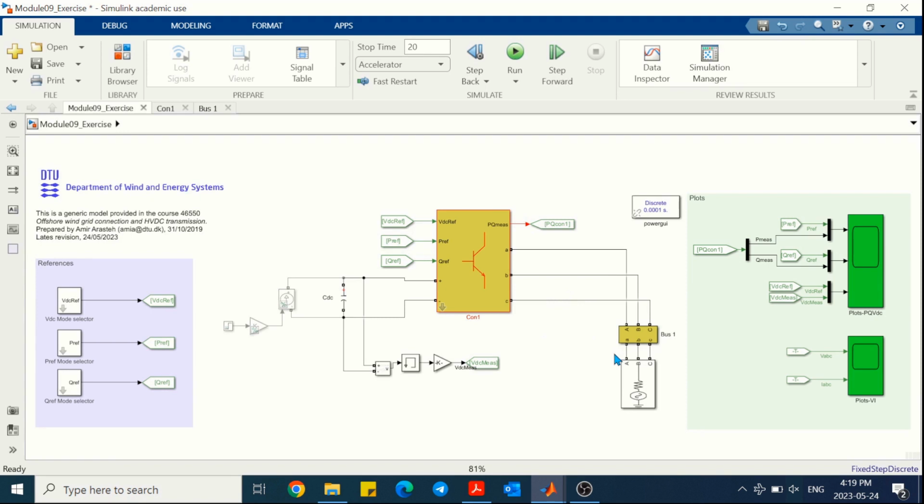So at this point, we have built this model, which consists of a capacitor with a converter and connected to the grid. And as we saw, it is able to follow the set points of reactive power. Probably you have recognized this is a very famous component in the power system, which is actually a STATCOM, and STATCOM is able to provide reactive power simply by a capacitor and a converter.